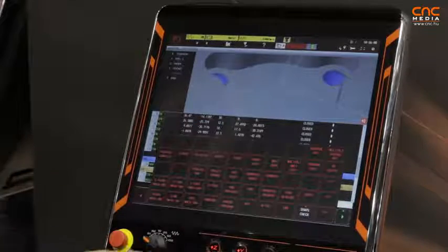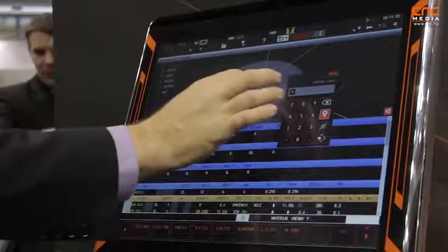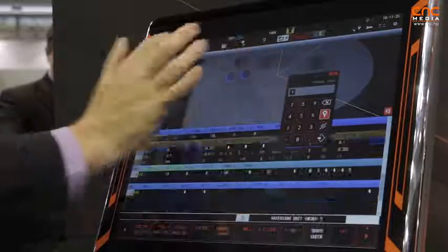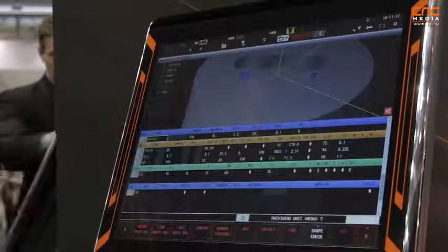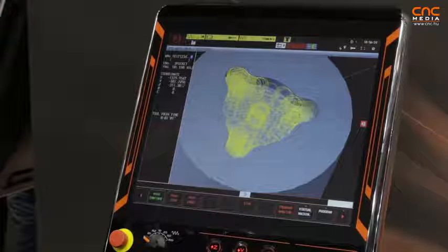original condition. The great thing about this though is this series here of design is interactive and associative features. And if I choose the drilled hole, it automatically finds the position in the program for the drilled hole. We can then do a tool path and you can automatically reproduce the path of the tool. That's looking at a Mazak program.